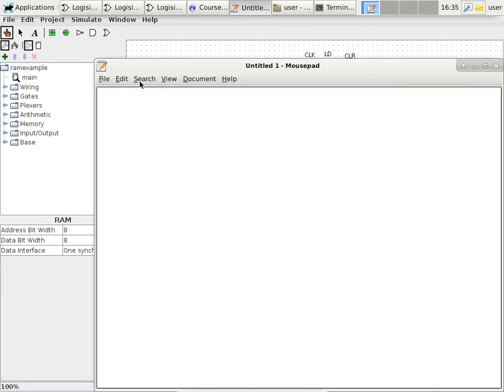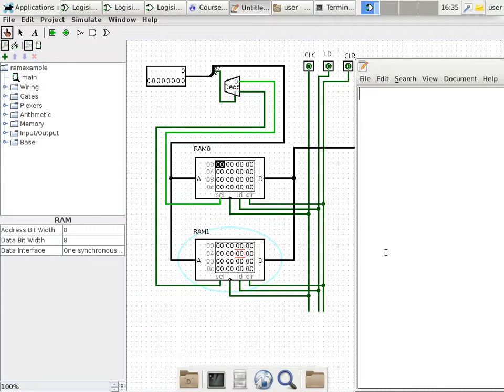Okay. All right. So we want to store a value of 7E in hexadecimal into the location that is appearing in red right now. It's highlighted. Okay. So it's a write operation. Remember, when we specify a read operation or write operation, they are specified from the perspective of the processor, which is invisible in this case because you are the processor. You are the one who is controlling the memory bus, and trying to specify the correct values of all the different pins. Are we doing okay so far with that assumption?